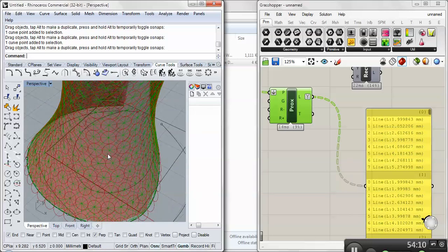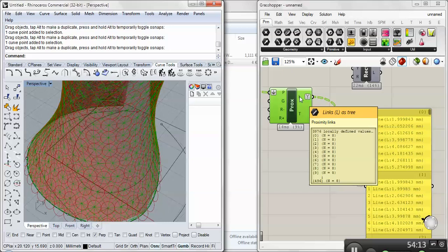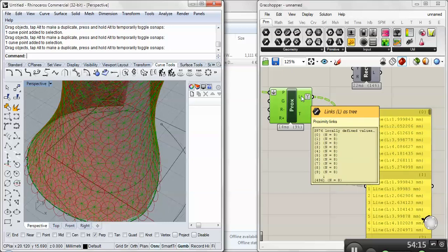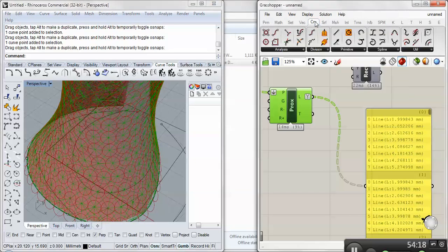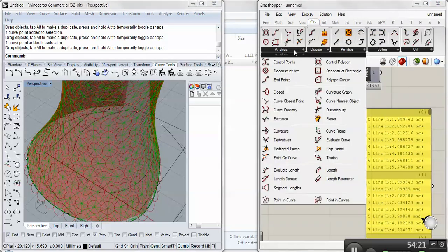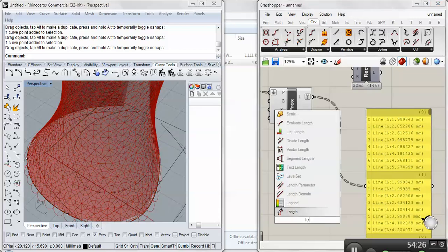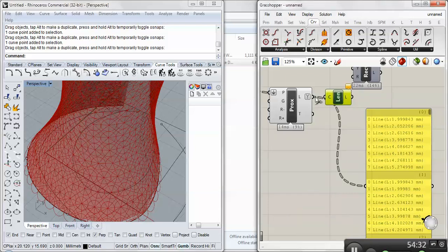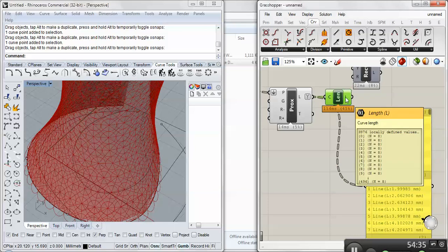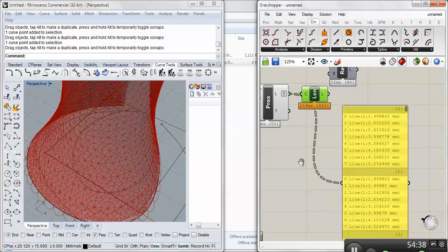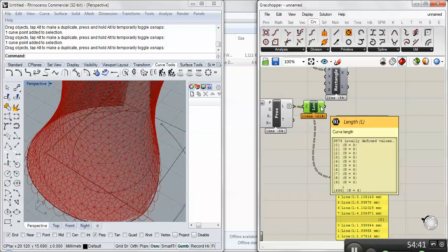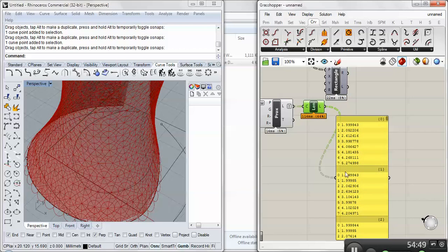And for our purposes, we care about distance. So even though it gave us this geometry, we'll go ahead and right away convert all those lines into a length. So curve, tab, analysis, you can grab length. You can double click and grab length. It's just measure the length of a curve. So the data is structured the same. I still have 496 individual points and then 8 lengths associated with that. I can drag that over, and now I have all these.